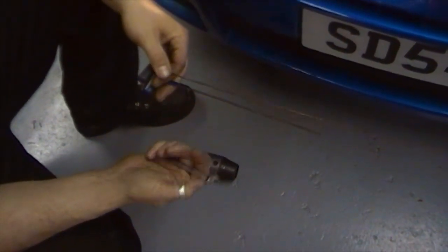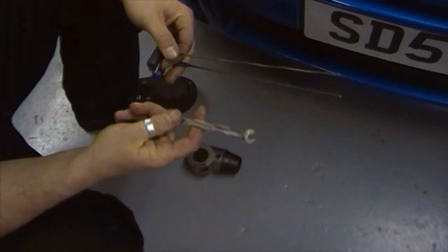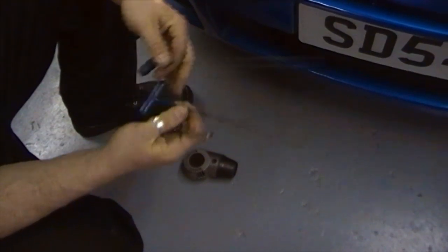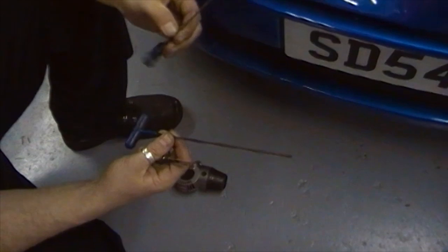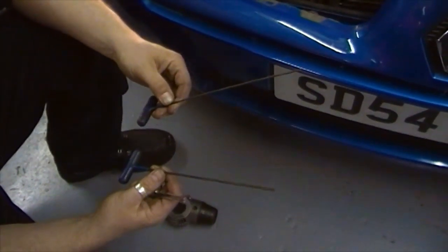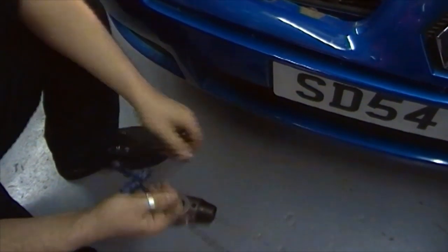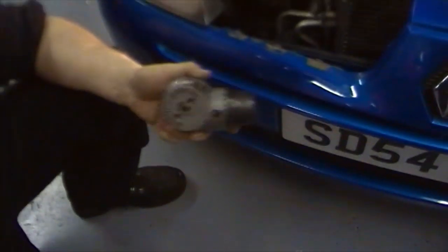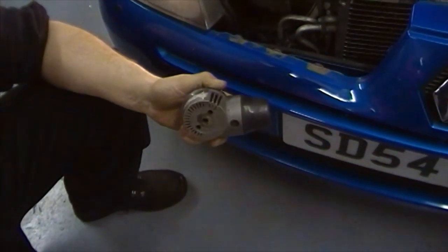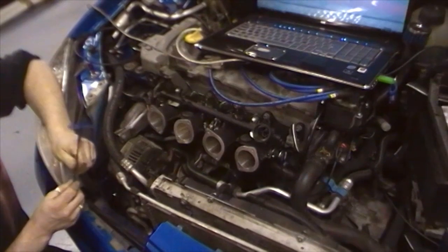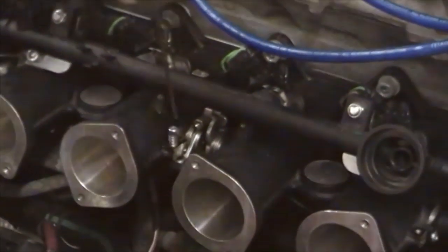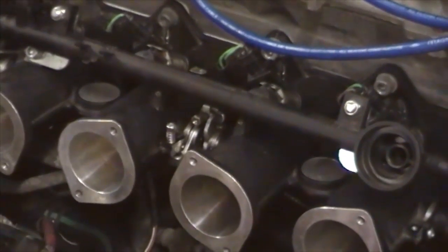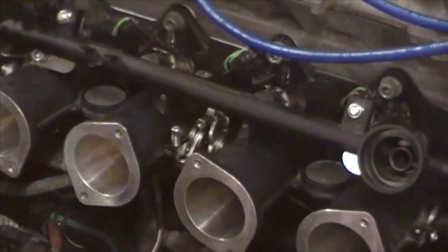Now, the tools you need for that are a 7mm spanner for the lock nut, a 3mm Allen key for the throttle body idle stop, and then a 2mm Allen key for the balance adjuster, and obviously the synchrometer, which we covered earlier. Now we'll show you how to use this. First, get to your throttle bodies. You may find that the throttle stop here isn't in fact slightly open, and you do need to open it slightly. Obviously there will be no air entering the engine.